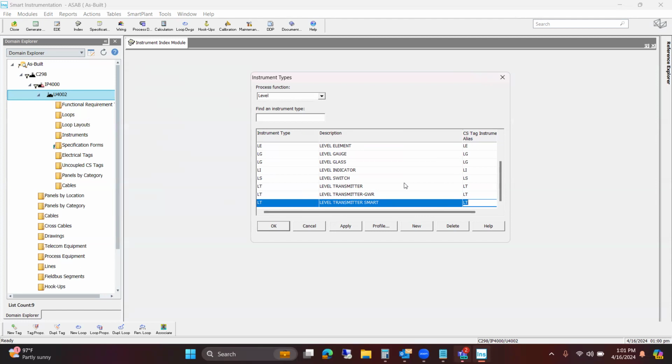Will only one person be working on the preparation of the instrument index or not? No, multiple other people will also be working on it. Each person's mentality will be different, because in the P&ID there won't be any rules that you need to capture the instrument like this. They will just be giving a hint.